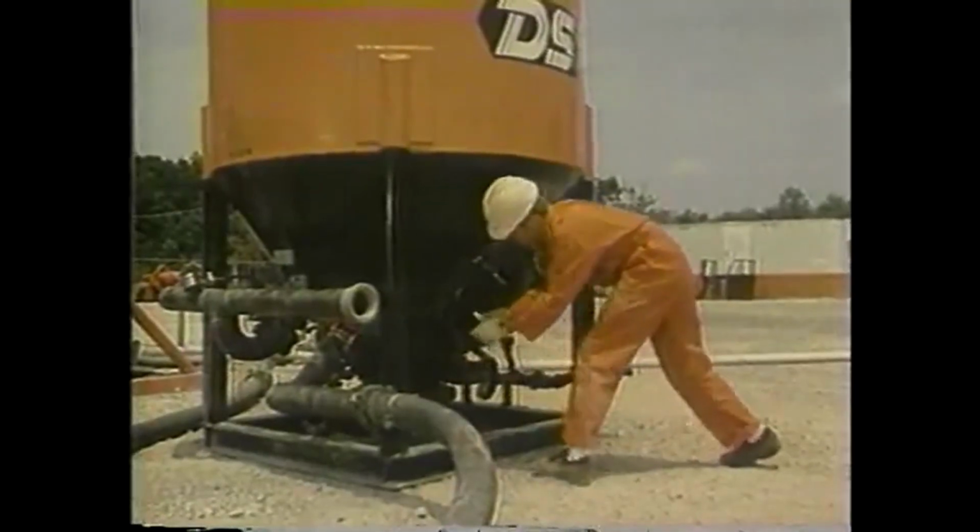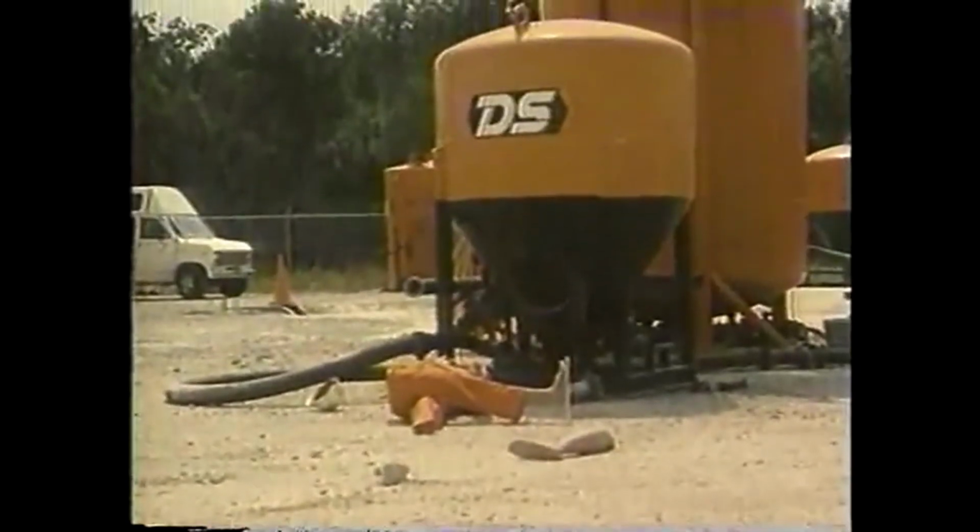In another event, recreated for Dowell cameras, a man was removing a hatch from a silo he assumed had been bled off, but a line was plugged. It only contained about 5 psi, not much pressure. But when he loosened the last bolt, well, watch in slow motion at what 5 pounds of pressure did to a mannequin. In this event, the man was not killed, but he did suffer numerous broken bones and internal injuries. He spent agonizing weeks in the hospital and longer still recovering.